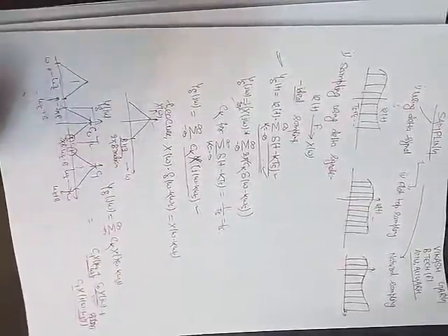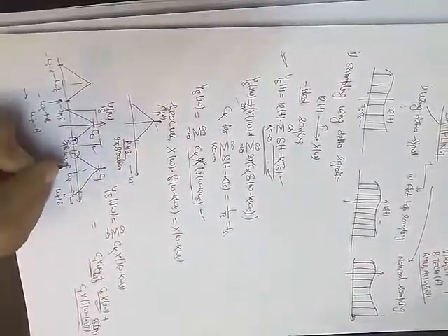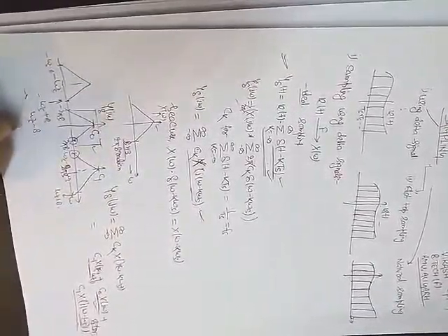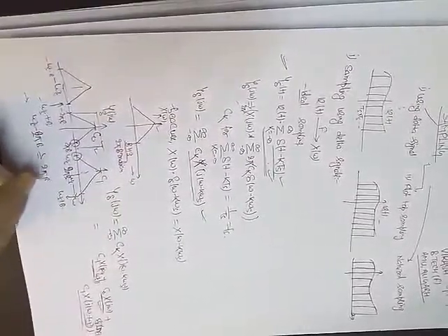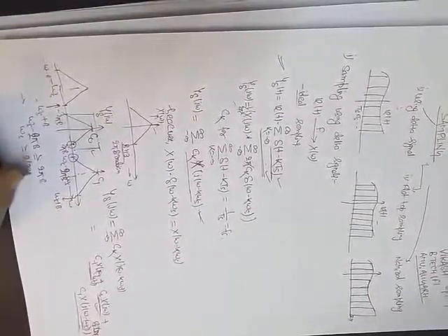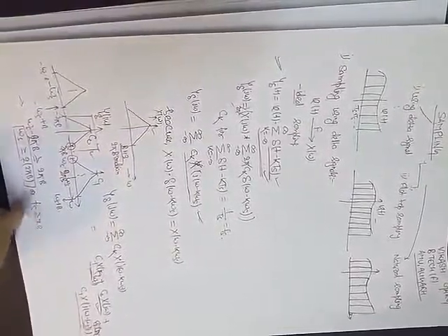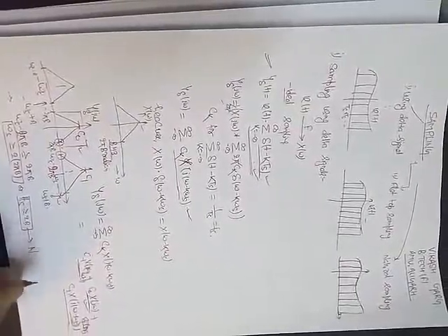So to get the same signal, we use a low pass filter of this much bandwidth. We should take ωs − 2πB greater than or equal to 2πB. So from here, ωs should be greater than or equal to 2 times 2πB, that is the message bandwidth, or fs should be greater than or equal to 2B. That is the Nyquist criterion of sampling.